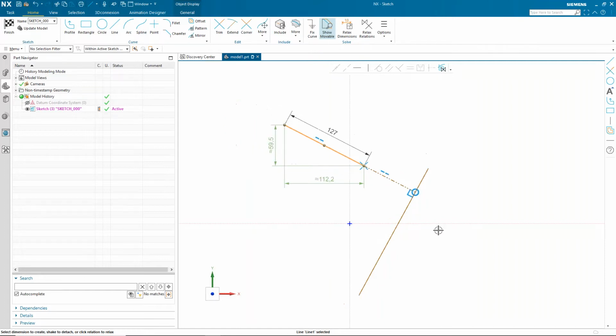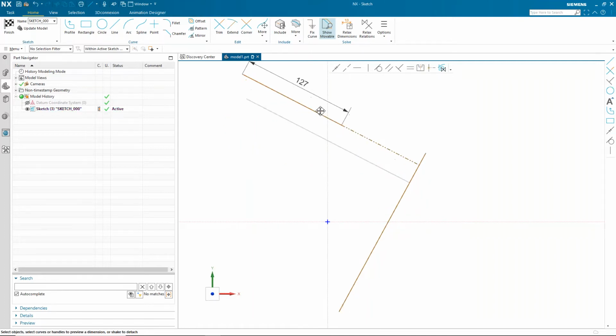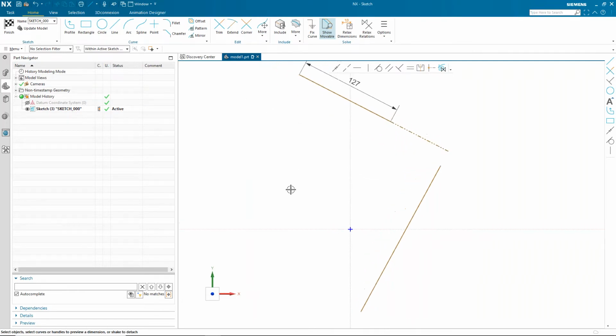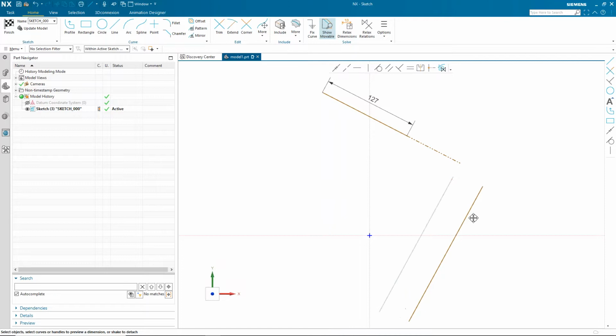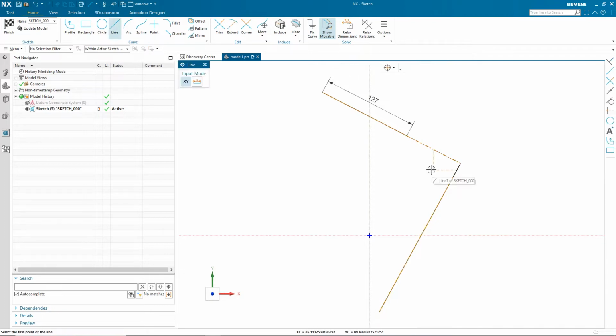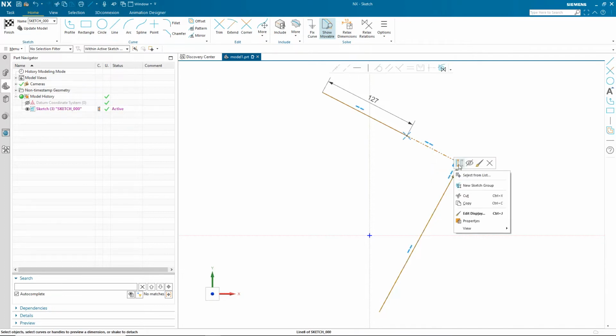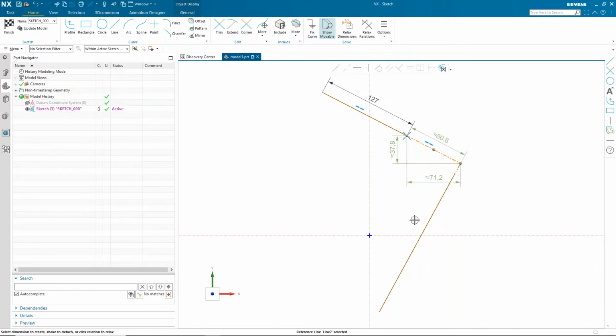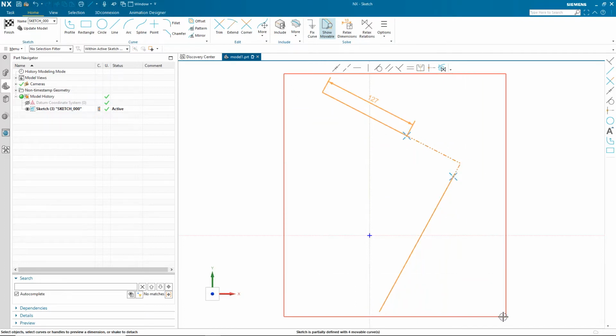This is kind of the same thing as before. If I move this one around a little bit and pull it off, they were kind of remote. They're connected, but now they're not connected perpendicular like we had them. So I can go back and create another line that I actually want those two lines to be perpendicular all the time, make it reference, and then everything is perpendicular. So I got all that. I'm just going to delete all these curves.